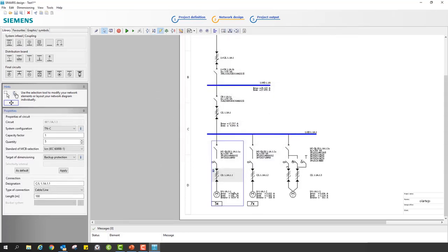Because I'm making my cable bigger, and when I have a bigger cable, the power can transmit more easily from one side to another, meaning the short circuit energy can flow in a much easier way in a bigger cable than in a smaller cable. You see? So here, I cannot see the attenuation, I'm amplifying the short circuit fault.